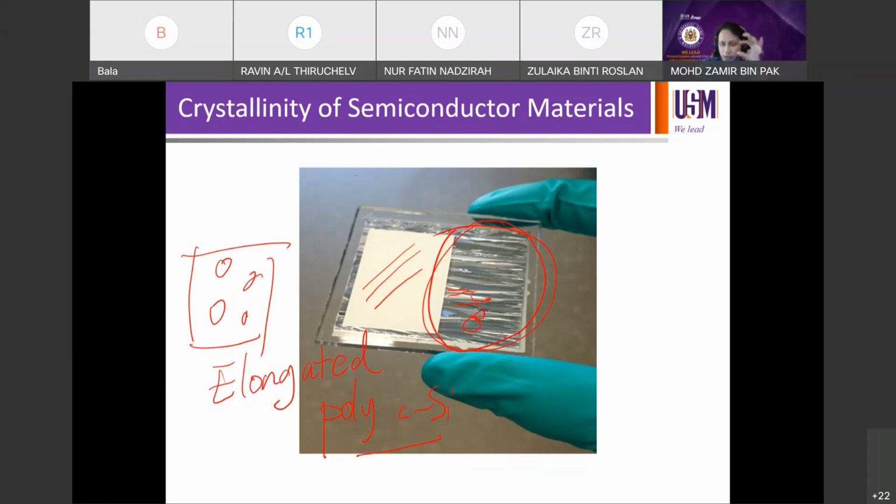For your information, just to put things into perspective, this silicon was originally deposited as amorphous silicon. When I did the deposition during my PhD, it was amorphous silicon. If you draw this from cross section, looking from the side, this is glass substrate. This is originally amorphous silicon, and the thickness is about 10 microns. So that's like 1/10 of our hair thickness, assuming hair is 100 microns in thickness.